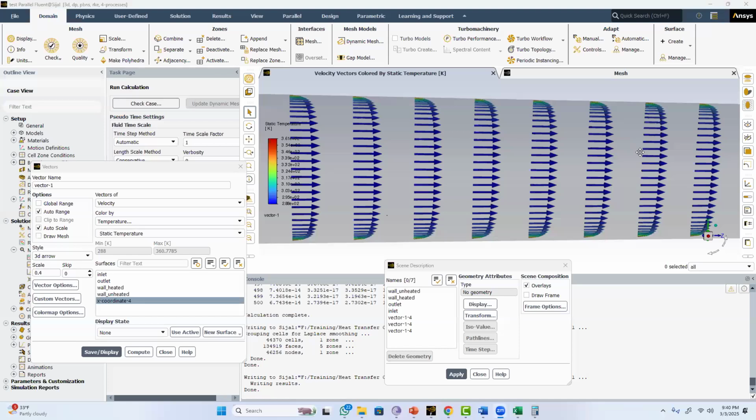Yes, it's only for turbulent pipe flows. It can be modified to be used for different cases; anywhere you see a pipe with turbulent flow, you can apply that. So here you can see high temperature here and low temperatures here. Every temperature we're talking about is the T bulk or the T mean temperature that we are trying to find out here. We are also trying to find the surface temperature, T surface, on the pipe wall. It should be on the same location as well.